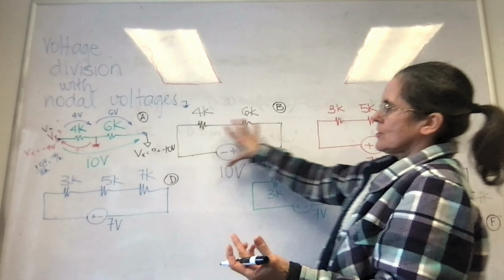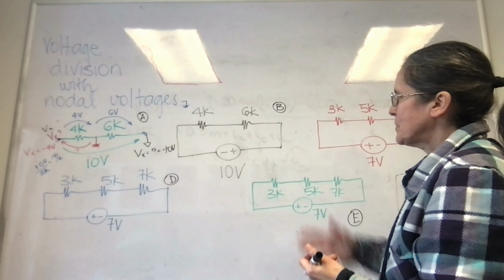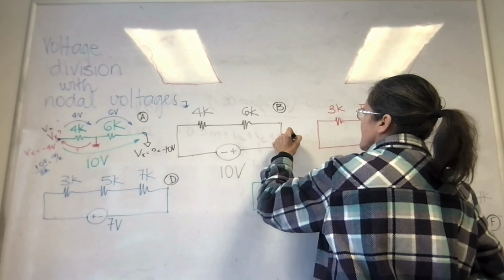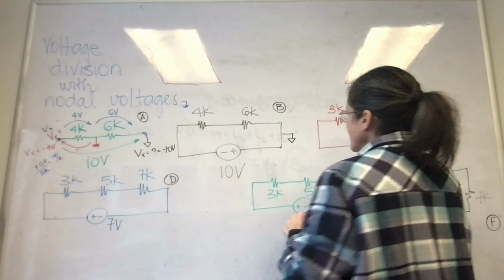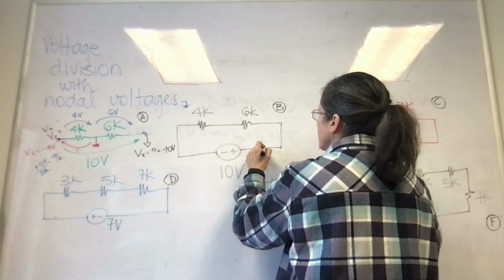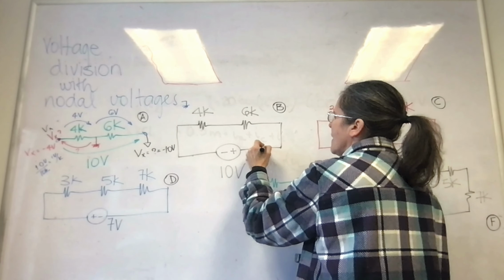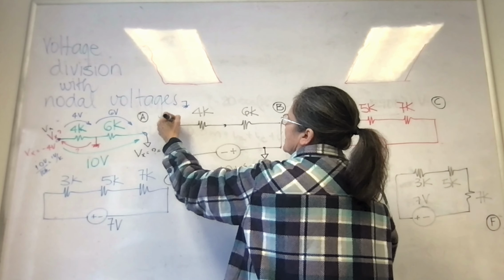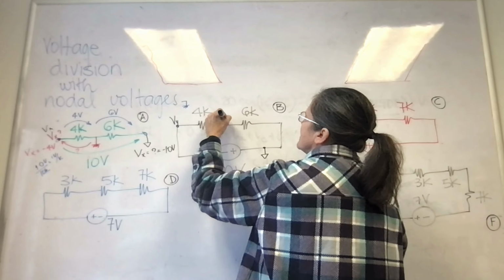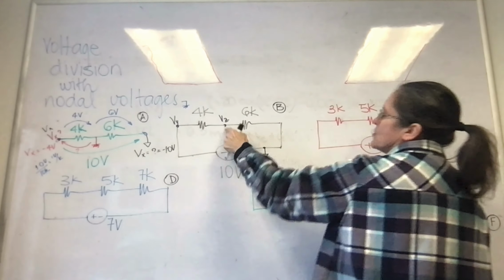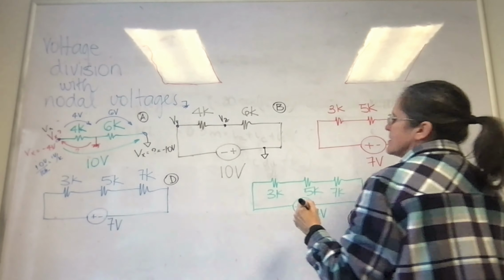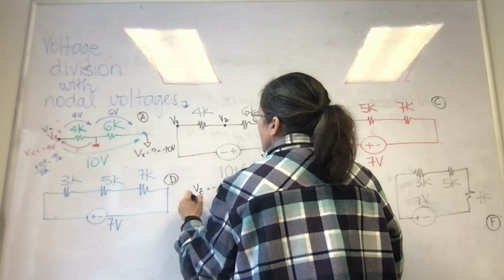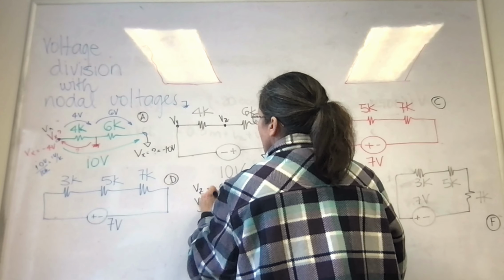Actually, the same thing can be drawn as a circuit like this. Maybe actually I drew it this way. So I'm gonna ask again sort of the same question. If my ground is here on this node, on the circuit B, what happens is all the voltages that I ask, for example, VY and VZ, are in relationship to this, and it turns out then VZ is minus 6 volts and VY is minus 10 volts.